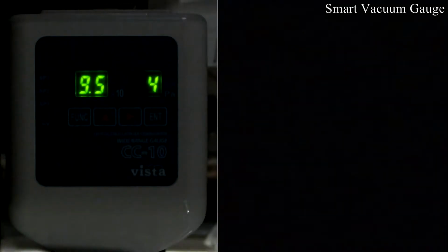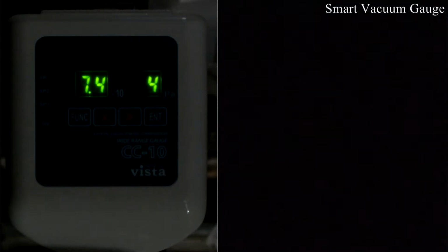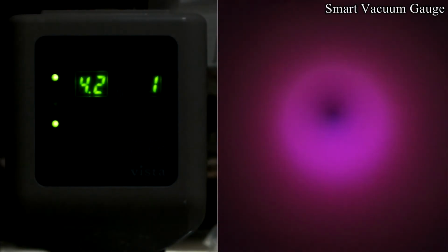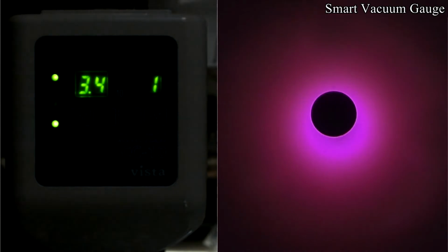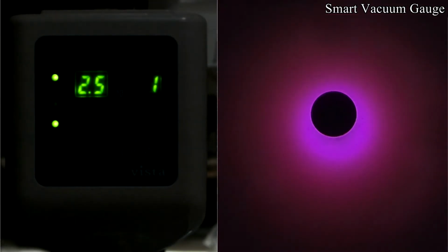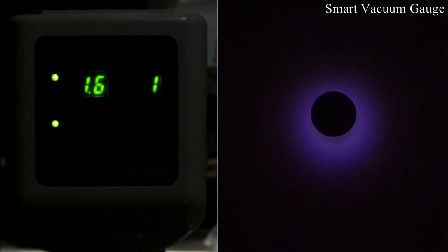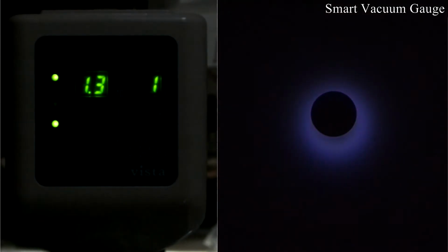Start pumping down from atmospheric pressure. The total pressure measured by the full-range gauge is shown on the left. The electrical discharge starts automatically at about 400 millitorr. Nitrogen and oxygen are the main components during the initial evacuation, therefore the electrical discharge is a reddish color. As the pressure lowers, nitrogen and oxygen decrease, and, as the water vapor becomes the main component, the electrical discharge changes to a whitish color.